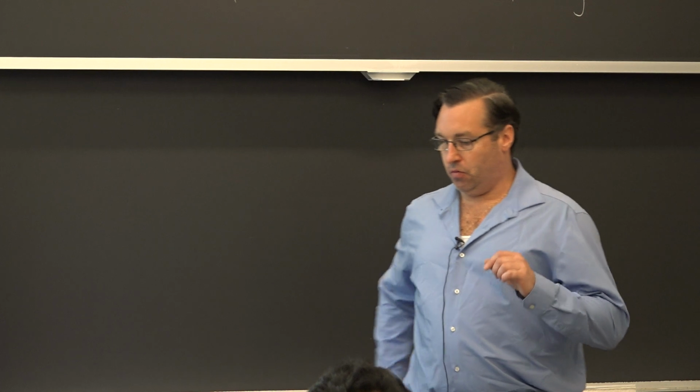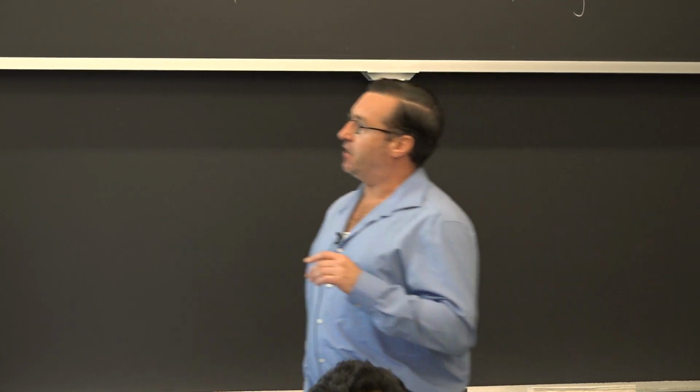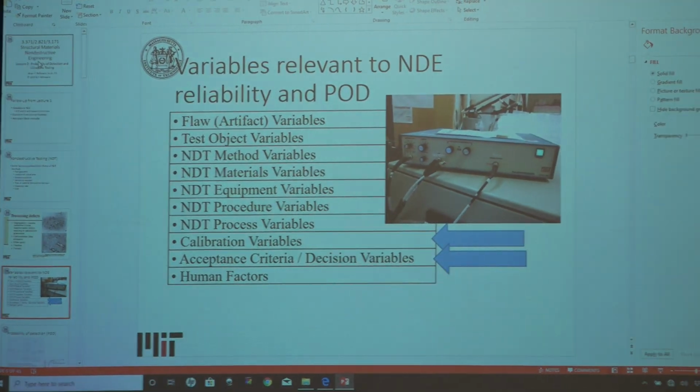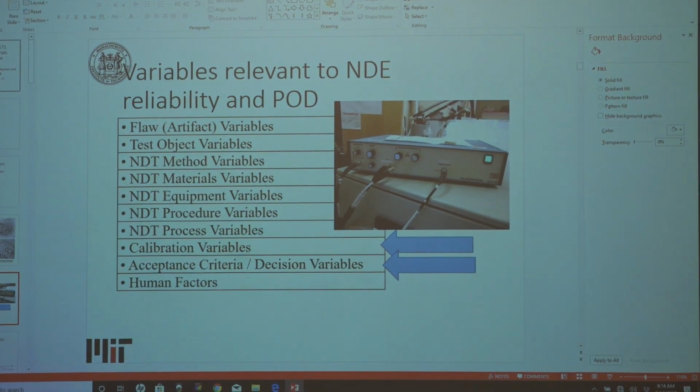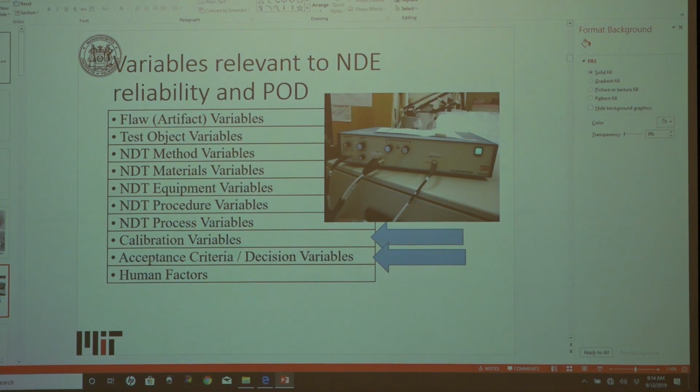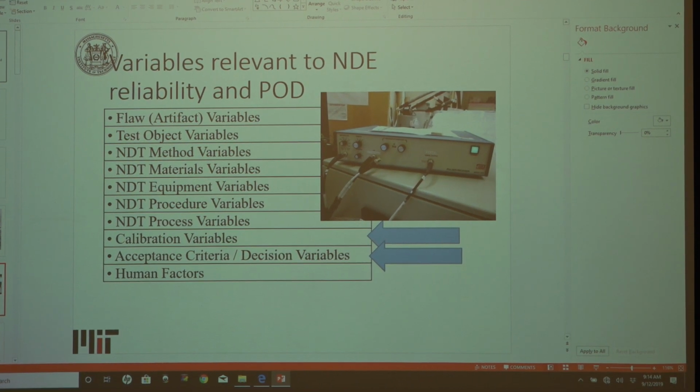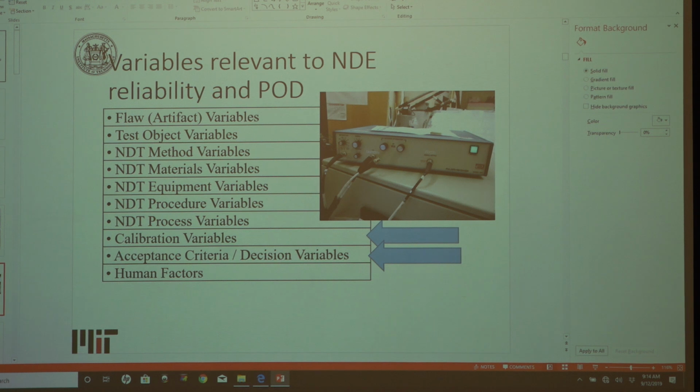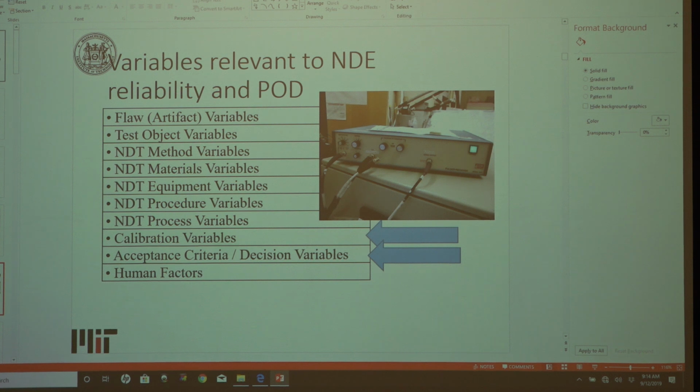So variables relevant to the probability of detection, okay? There's not just material considerations based on the alloy selected. With non-destructive testing, there's considerations on the sensitivity of the equipment you're using. So for some sensitive government type projects, the electrical noise from the equipment selected can be enough to lead your signal to noise ratio to be inadequate.